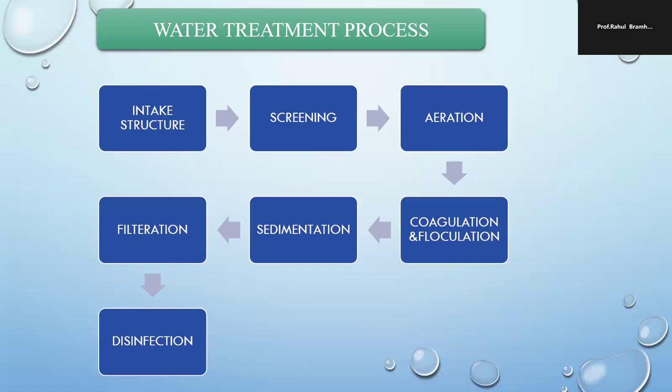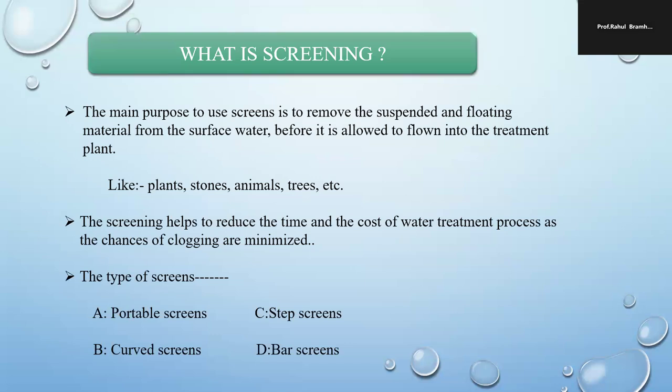Firstly, intake structures. What is meant by an intake structure? An intake structure is a structure made of RCC or concrete, constructed near a water source, so that with the help of that structure we can take water from the various water sources and pass it to the water treatment plant.